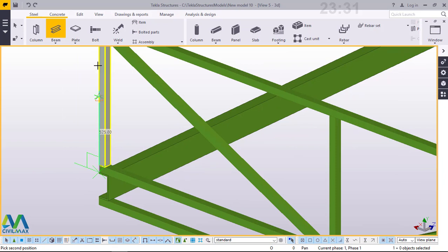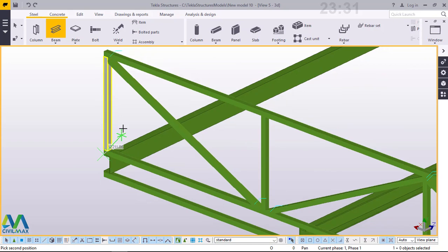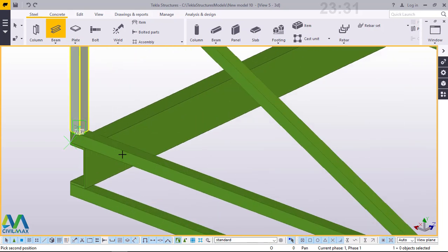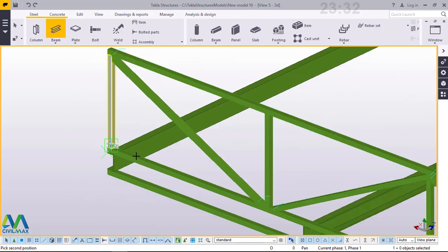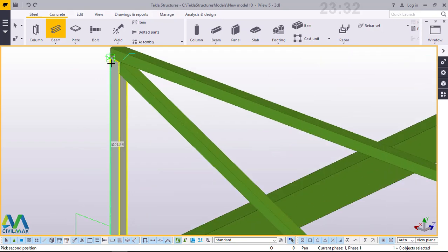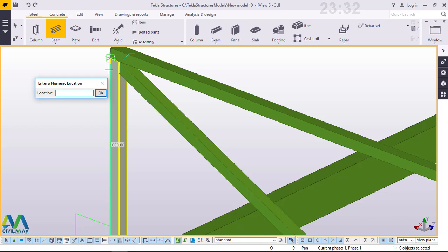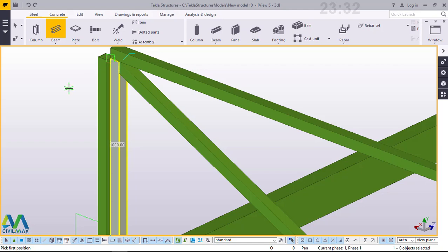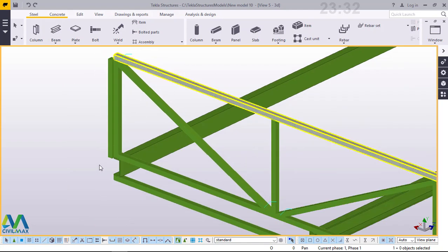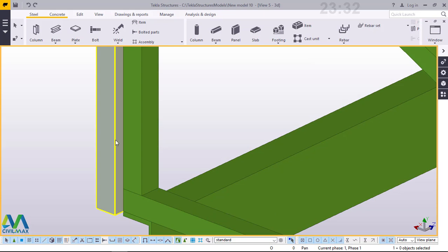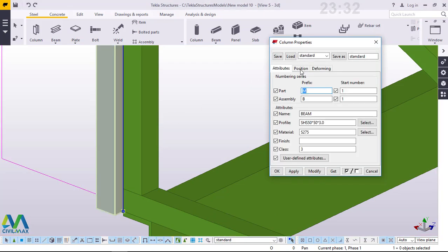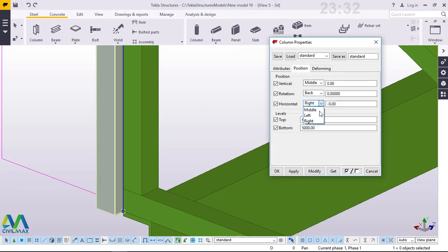and I'll feed. The size of this member is 50 by 50, plus the height of this member, this is 950, making it a meter. Now what I'll enter here is a meter. I'll enter 1 meter, and enter on my keyboard right there. I'll use 1 meter, double click on that member and give it a position. I'll take it to middle,